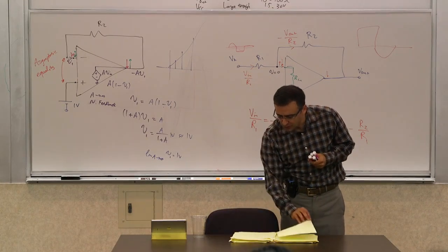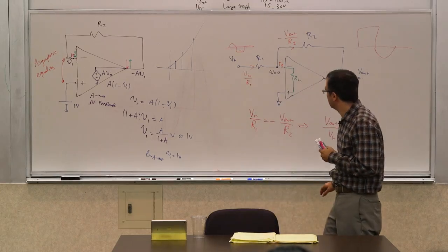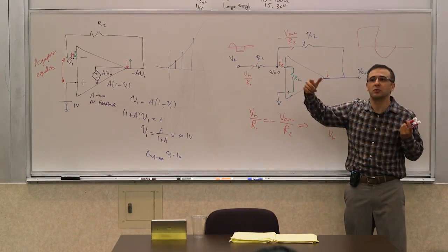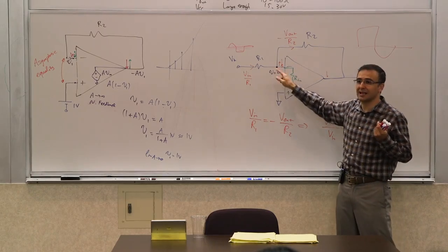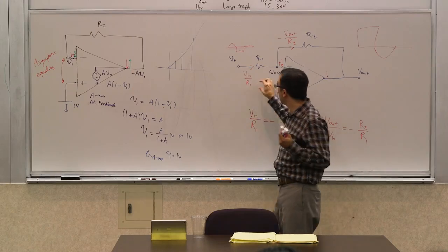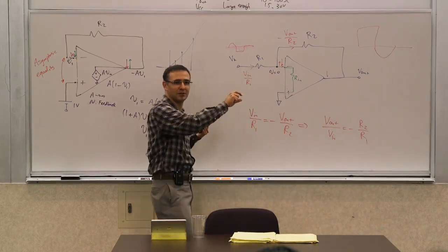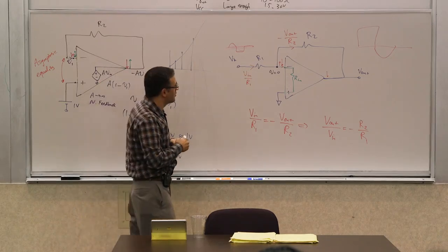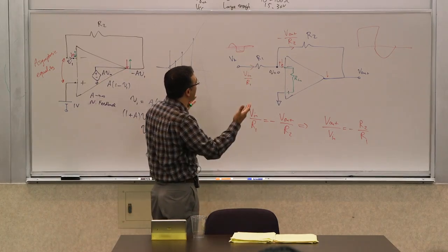Now, you can see even that resistor doesn't matter. You can redo this calculation with the resistor. And I think one of your homework problems, you will do that. Do your KVL, KCL, and write this and show as A increases what happens to this voltage. You actually will monitor this voltage and see what happens for different values, so you get a better sense of what this really does. So that's an inverting amplifier.